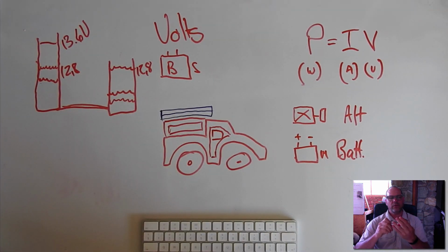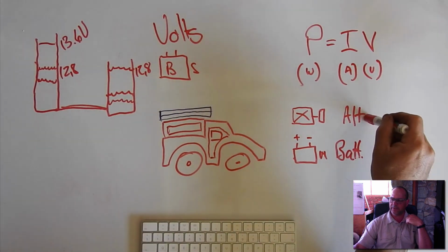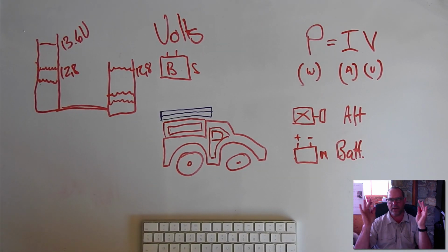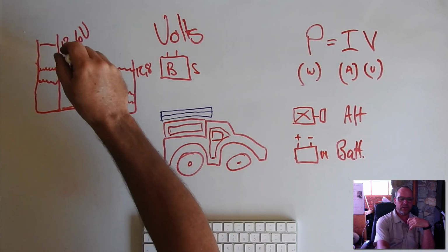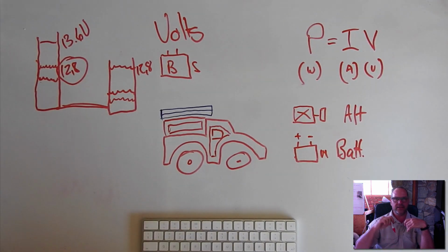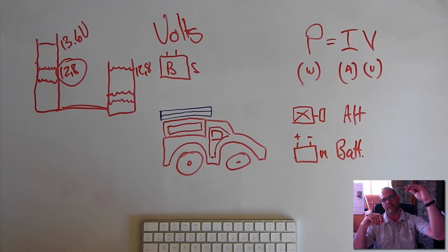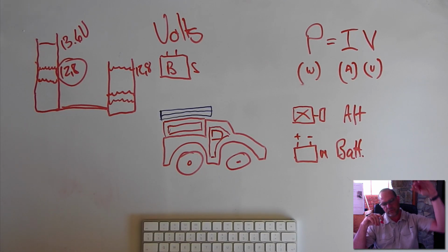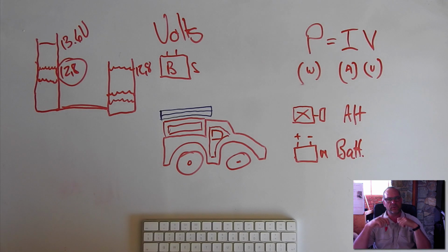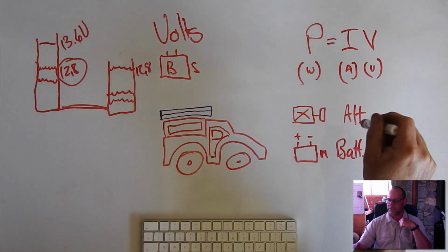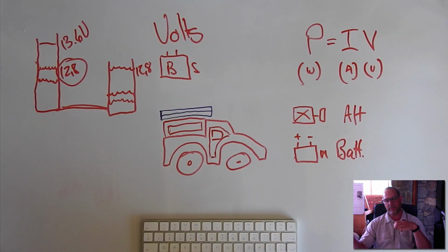So you'll always see that your charging side, your alternator, your battery charger, whatever you have charging, will always charge higher than 12.8 because it needs to create that additional height, the potential difference, to push the power through to the charged battery. So when I say that you have two different sources to supply power, it is your alternator and your battery. Let's forget 220 volts.